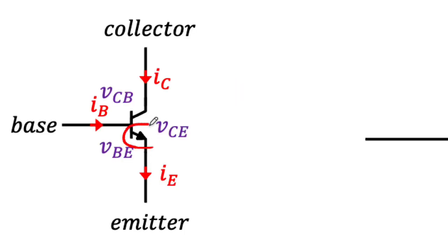So the arrow here has two different purposes. It indicates the direction of the p-n junction, thinking of that as a diode, and it also indicates the direction of current flow under ordinary operation. Now, we also have a p-n junction here, and despite what I just said, I am going to draw a little arrow here just temporarily. But again, you can't think about it as two diodes stuck together. This is a more complicated thing with more complicated behavior. So I am going to put a little arrow here just to indicate the direction of the p-n junction.